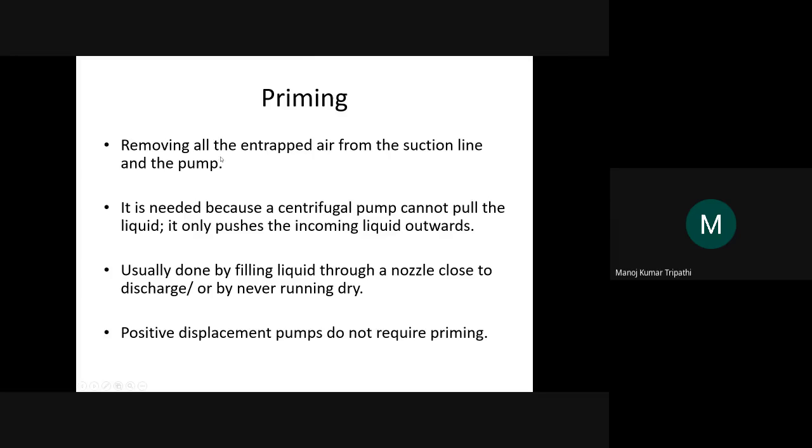So it requires removing all the entrapped air from the suction line and the pump. So the entire pump has to be filled with the water or filled with that particular fluid. Otherwise, it will not work properly.